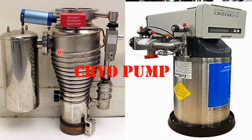It has advantages, dear students. A cryopump usually uses liquid nitrogen, and its temperature is somewhere around minus 170 degrees centigrade. This very low temperature makes the cryopump act as a sink for the impurity available in the reaction chamber of molecular beam epitaxy.